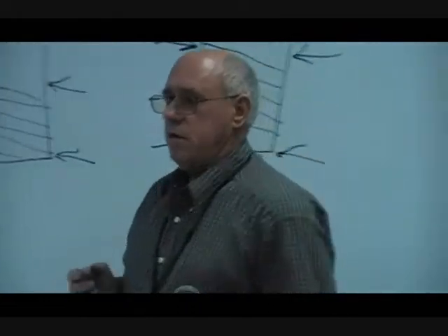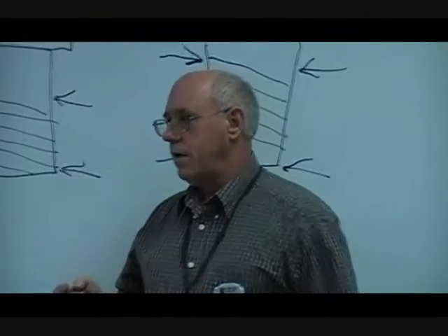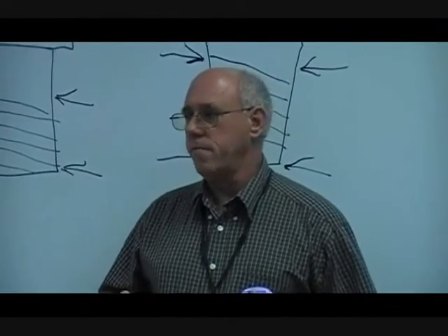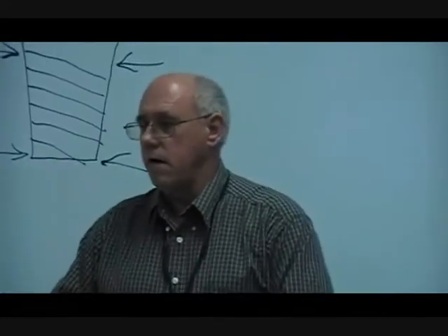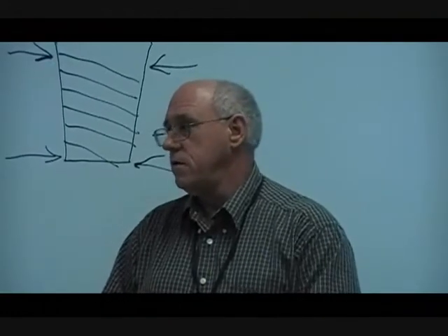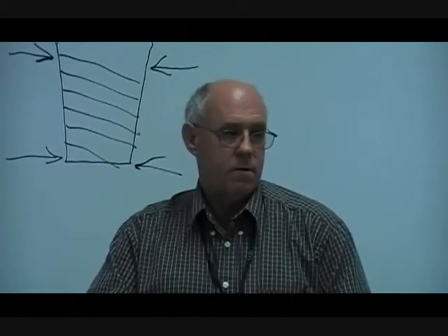Okay, where do you see that being a problem? What if somebody uses a fitting or a valve that is rated for water only on a gas line? Natural gas can go places that water won't. It can escape through the small hole. Some gas fittings cannot be used or may not be rated for water. If you use a gas fitting on a water line, you're bound to have a problem. Okay?